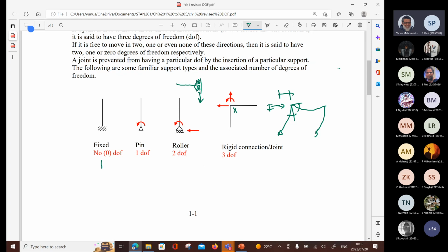Are you following what I'm saying? But horizontally, it cannot move. It won't allow movement that way. Don't think of reactions, think of movement. Okay, all right, so the roller will allow this thing to rotate. It'll be free to rotate. It's a pin, okay, and free to move vertically, but it cannot move horizontally. So I've got 2 degrees of freedom, right?